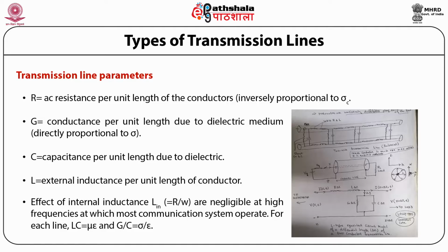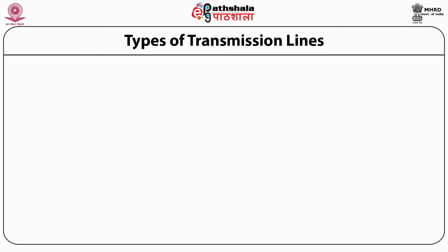So now the Poynting vector, that is E cross H, points along the transmission line. Closing S creates the disturbance resulting in a TEM wave as shown in this figure. Let us now derive or discuss the transmission line equations.